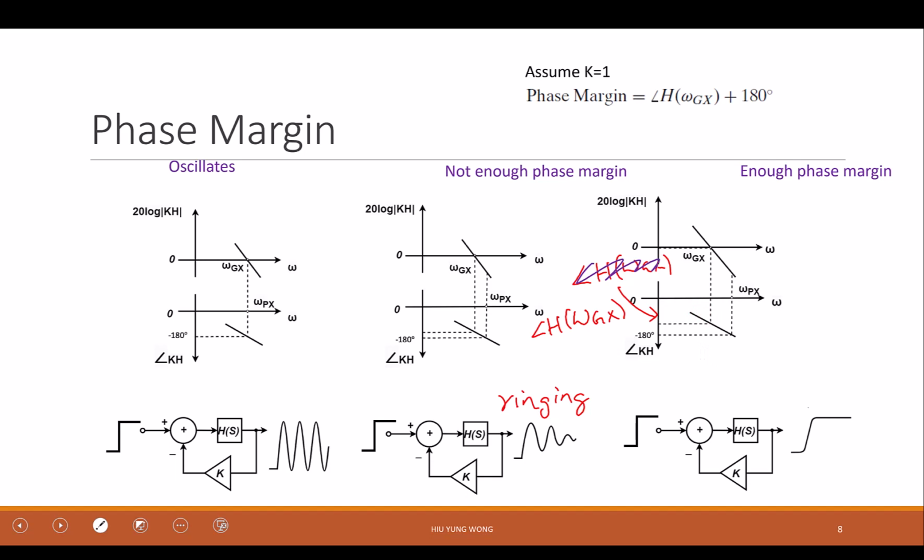Your question? The other question I had is, is there a rule of thumb for approximating a good phase margin, or would we have to evaluate system components every single time? I think usually people ask for 60 degrees for a good system. Yeah. And you are actually taking the graduate class, right? I think they gave you a margin. What was that in the project?